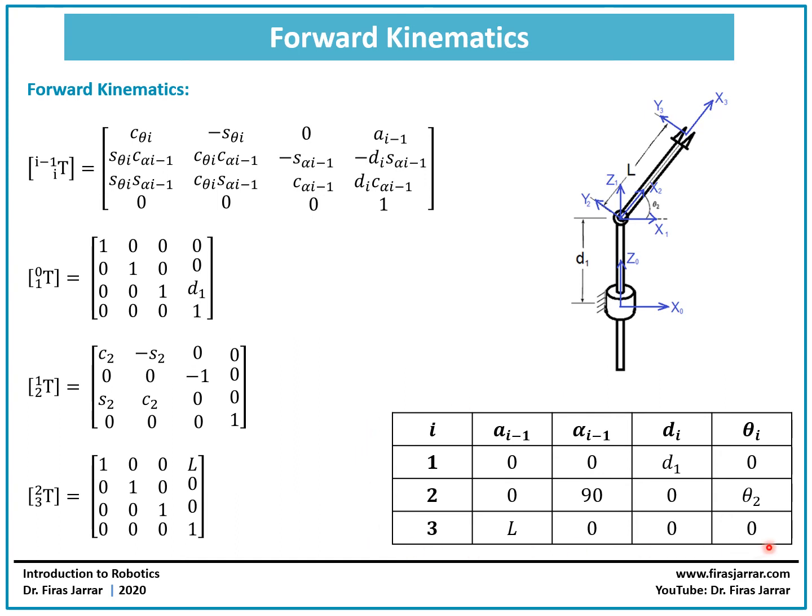So these are the DH parameters for this robotic arm. The next step in the forward kinematics is to substitute each row into the general homogeneous transform matrix for each link. So starting with link 1, we'll have T1 with respect to 0, the transformation matrix of frame 1 with respect to frame 0, and you need to substitute these values for theta, D, alpha, and A into this matrix. If you do this, you're going to obtain this result here for T1 to 0.